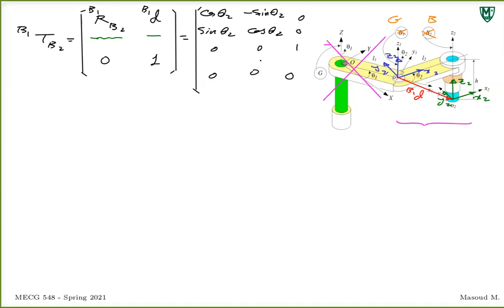Now we translate the coordinate frame, go from blue to green. That's what we're doing when we do transformation. Always start the body frame where the global frame is, figure out how many rotations you need to make it aligned with the final position of your body frame. Make axes align, and then do the translation at the end. So that's how I want you to think about this.